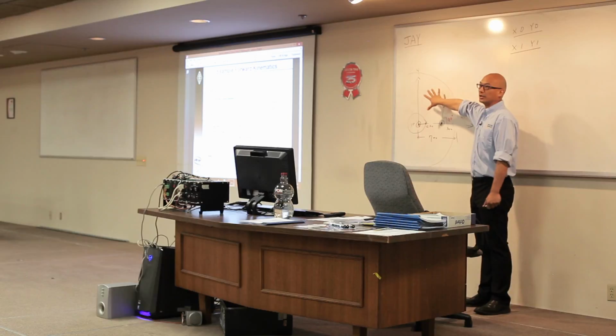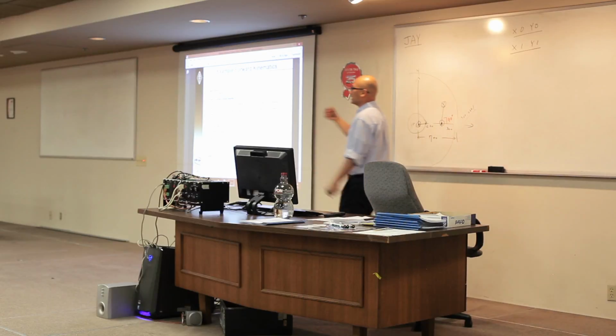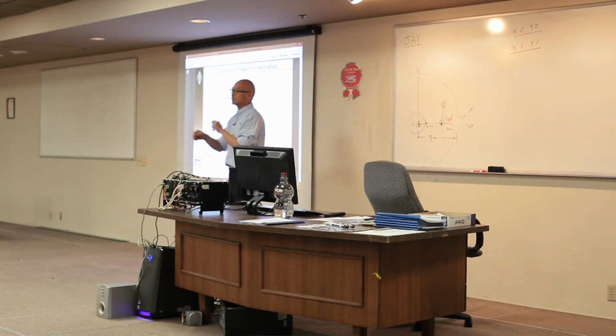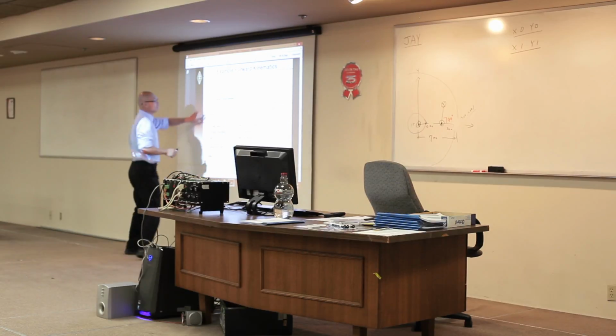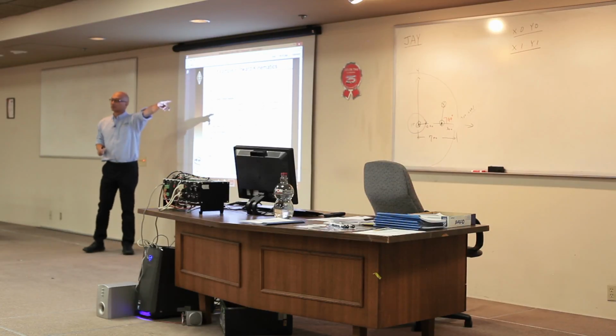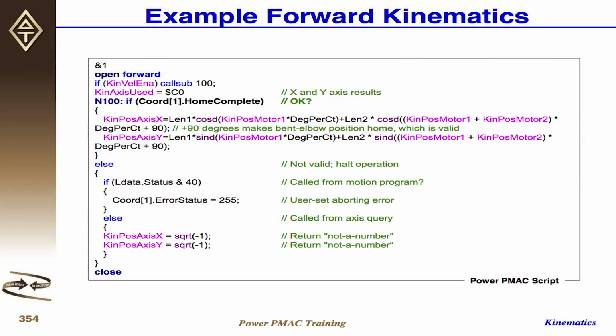That's within the range, no problem with inverse and forward kinematics. Okay? So when we actually get into a little bit more detail, the concept of forward and inverse kinematics are easy actually, but the details, that's what you are looking for. This is one of them. That's why we add 90 to make sure that the initial position is there, instead of just flat, 0 position, stretched out.